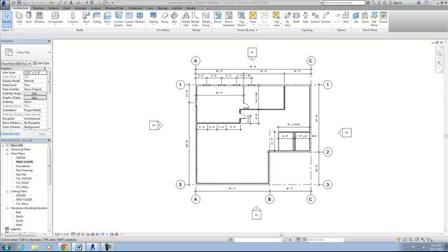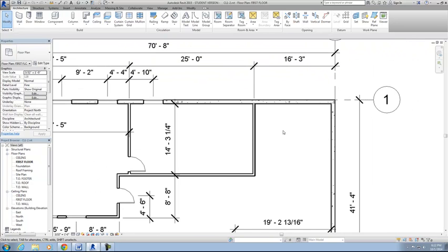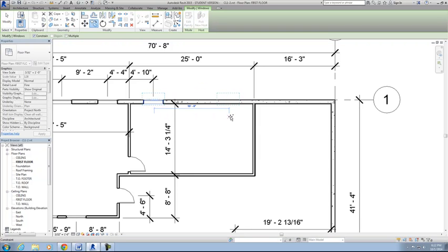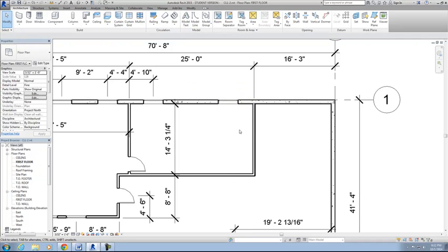So continuing on, let's go ahead and zoom in on the top right corner of the floor plan, and we're going to add in an additional window. So I'm just going to use this window as a starting point. This is window 3, the fixed 48 by 72, and then I'll just copy this. So you don't necessarily have to add in windows from scratch. You can go ahead and copy the element from another part of the drawing. And then we'll add in door C.